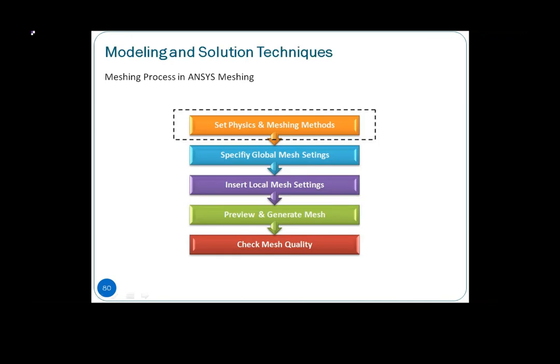Right. So in terms of types in ANSYS meshing, if you later on try the examples, I mean the case study itself, and you are in 2D, so you have to choose in your analysis that it is two-dimensional. Then only you will see the mesh types of two-dimensional elements, what we have learned, the triangular and the quadrilaterals. If you are choosing three-dimensional analysis, then you will see the three-dimensional types of elements. So this basically is the layer in terms of your meshing.